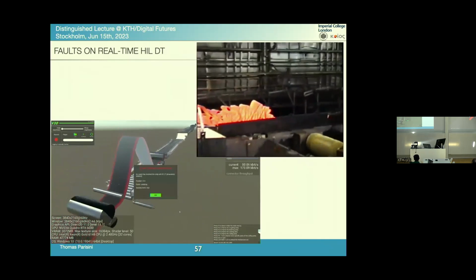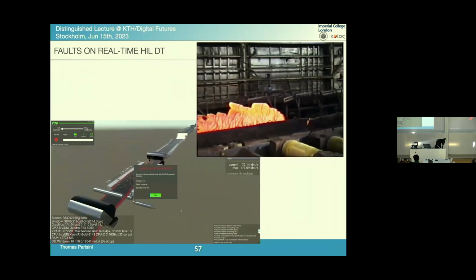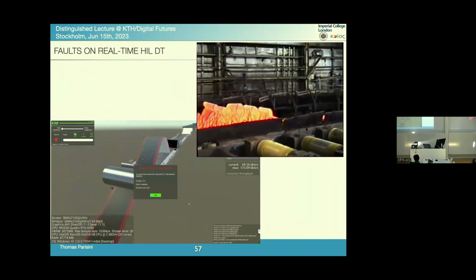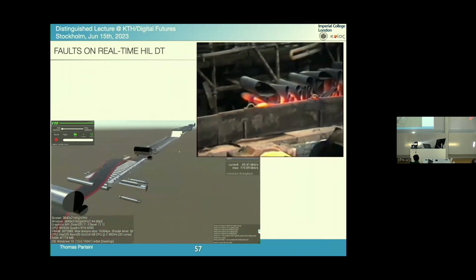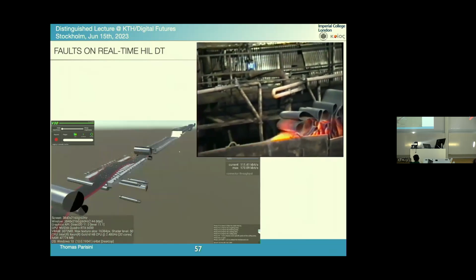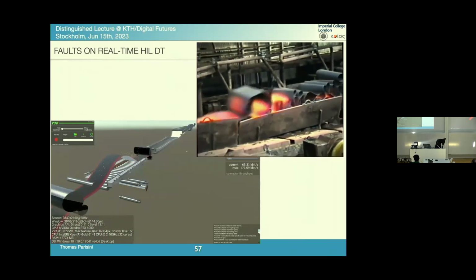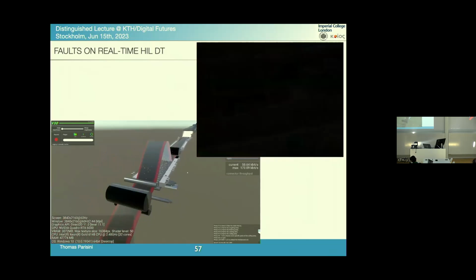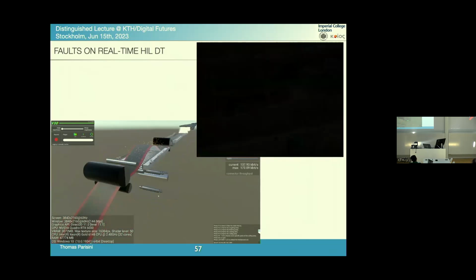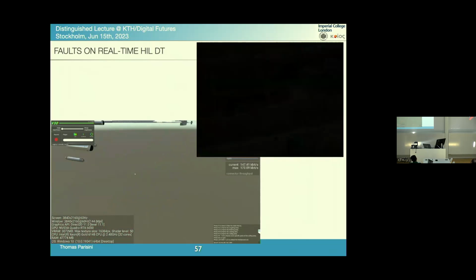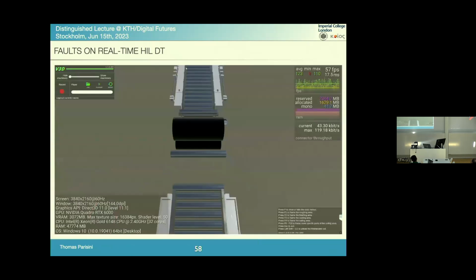And you are going to see that it is a real cobble that is happening, exactly this kind of phenomenon. But with the digital twin, you are able to predict that. And then here you see the recovery. So once there is a cobble, you try to recover. And here you see the digital twin is telling you how you can recover, how much you have to increase or decrease the speed of the coiler in order to recover from the cobble. And that was very useful for us to tune the controller that does the recovery automatically, because of course, that phenomenon is very bad if you don't.